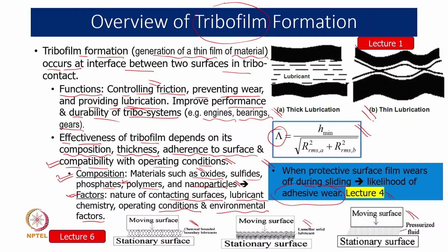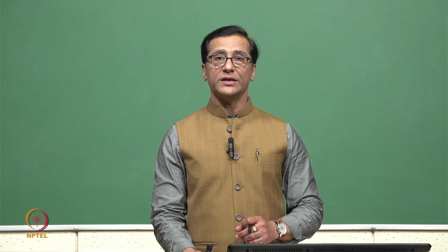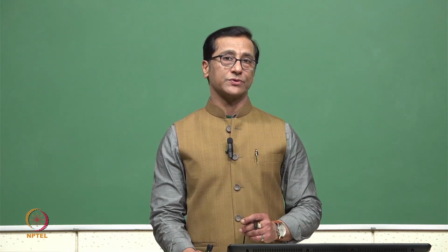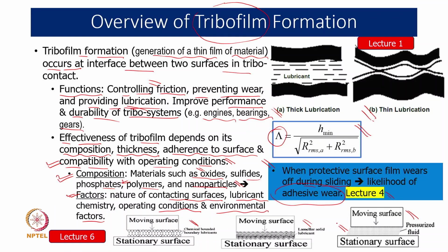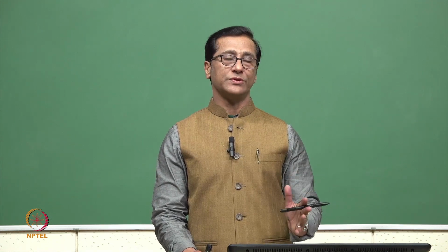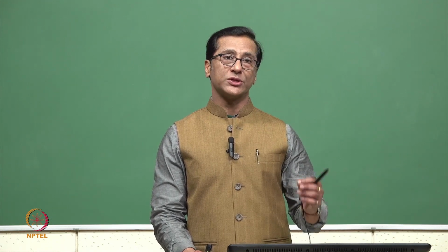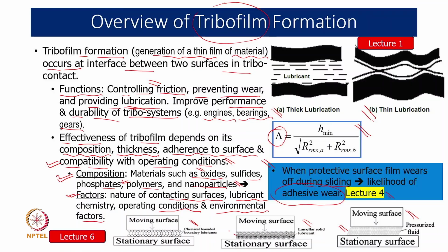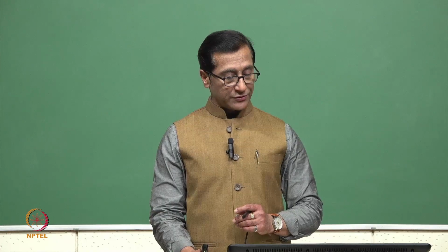The fluid can be hydraulic fluid or lubricant, base oils, or it can be air also. Now it can be self-acting or it can be pressurized. Both are possible. So we have various mechanisms to form the tribofilm. It can be thin, it can be extra thin also. It can be solid lubricant related, it can be air lubricant related also. It can be chemical agents interplaying between the surfaces or interface. So we have a variety of tribofilms which can be formed at the interface.